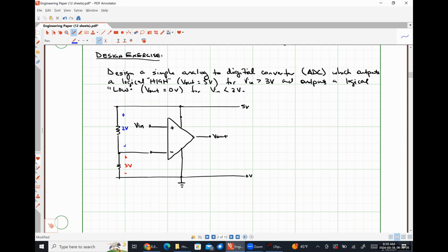Which means if we are going to use a resistor network here, we want to make sure that the resistors that we use are significantly smaller than the megaohm scale so that effectively none of our current flows into that terminal, which would mess up our voltage divider relationship, okay? So we need resistors that are significantly smaller than megaohms over here.